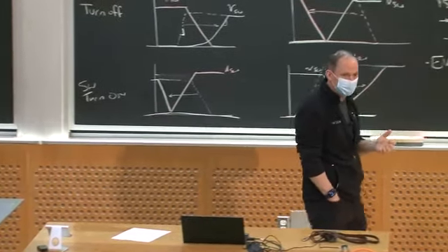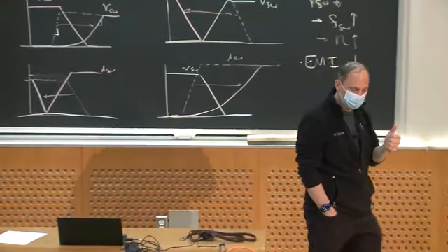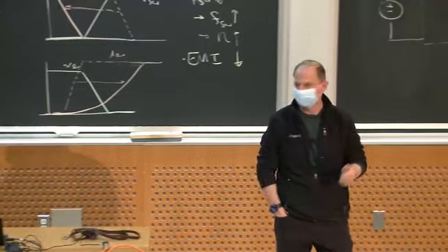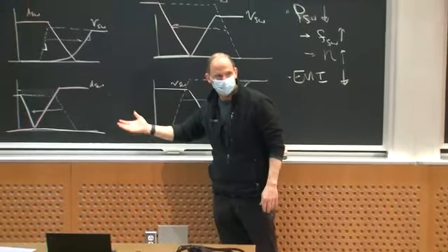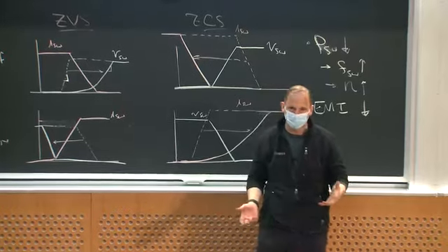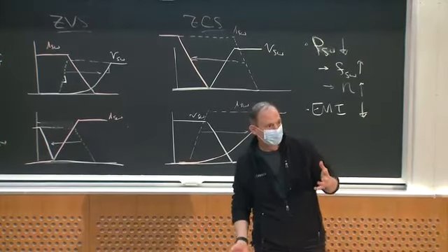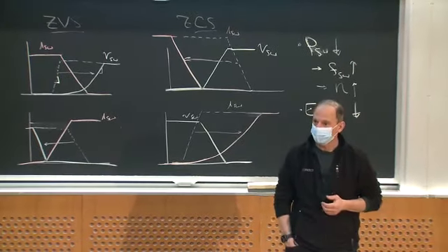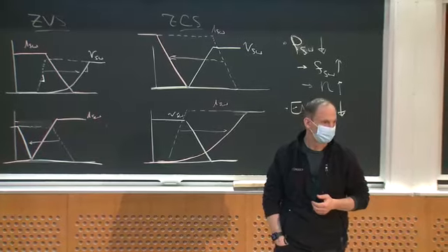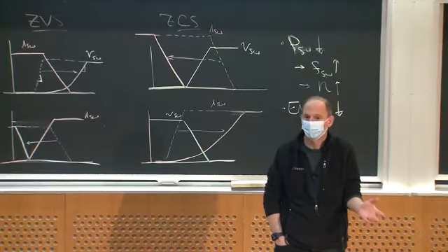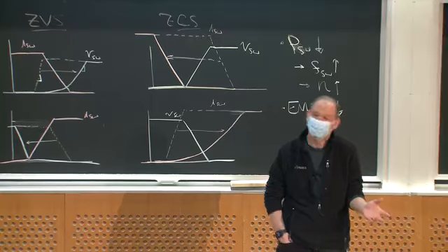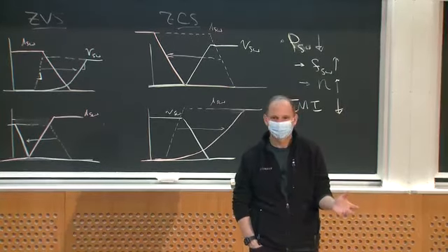What's a good way? Well, it depends upon, first of all, your device characteristics. I make it sound like all devices are the same, but it turns out they're not. So what soft switching technique might really be suitable does relate back to the details of the type of semiconductor device you're using. There are some devices that just don't like to turn on under 0 voltage, so you probably wouldn't want to use 0 voltage switching for that kind of device.